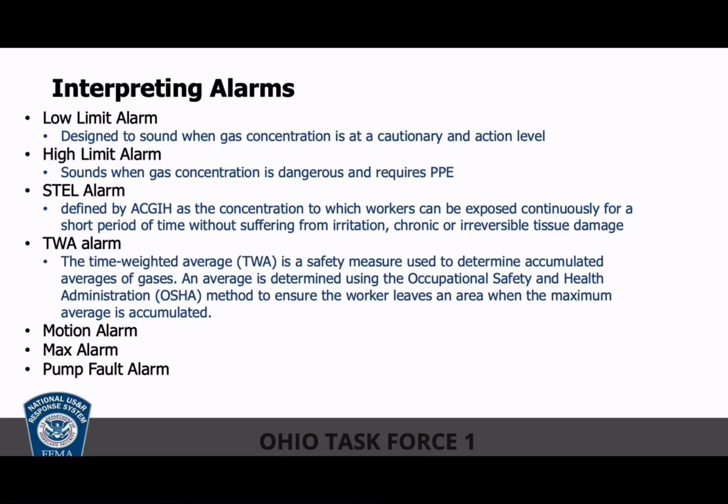When we get to a high limit alarm, it's saying this gas concentration, regardless of what it is, a flammable gas or not, is dangerous, and it requires you to be in PPE to be able to keep moving forward with what we're doing. A STEL is short-term exposure limit. This is a term that was defined by the ACGIH, the American Conference of Governmental Industrial Hygienists.